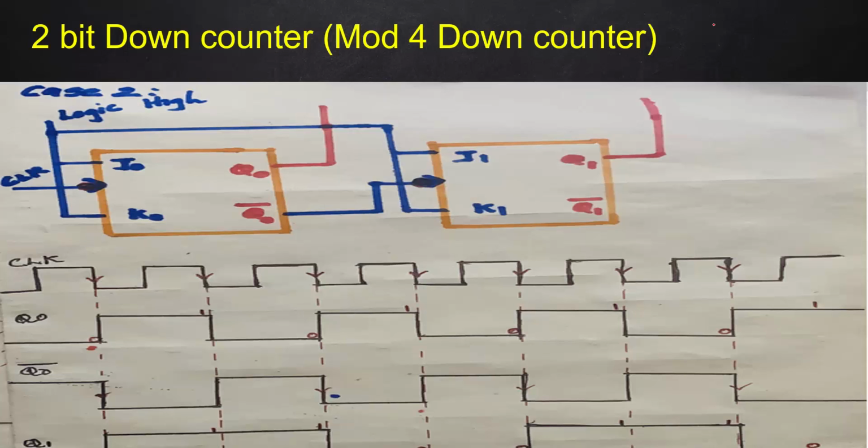Okay, next is about down counting. This will count like 3 2 1 0, again 3 2 1 0, descending order of counting. So how can we change this circuit for asynchronous down counting? In our previous case, we considered the Q output as clock to the next flip-flop.